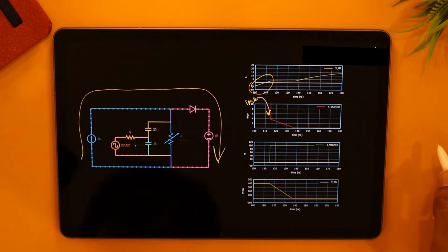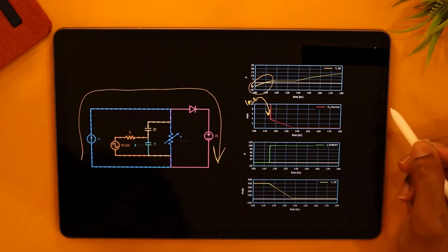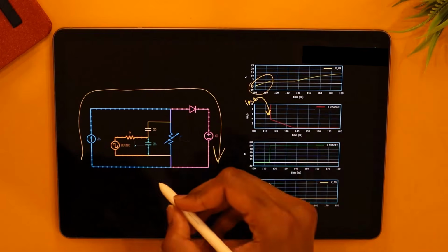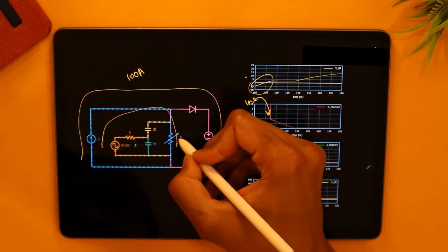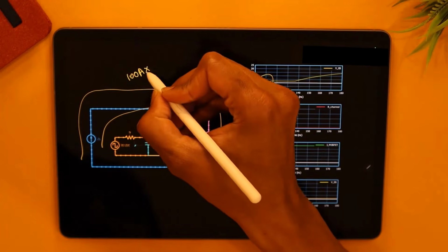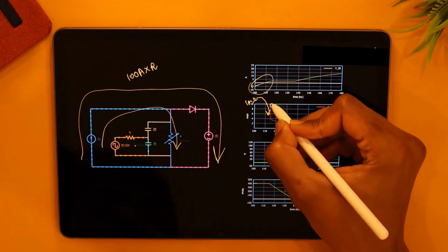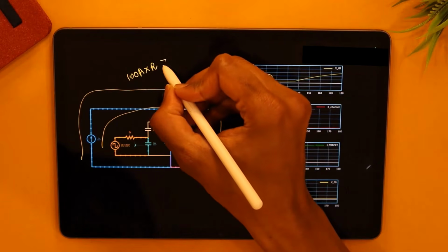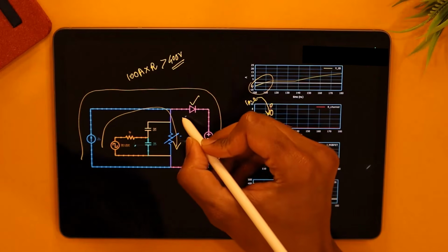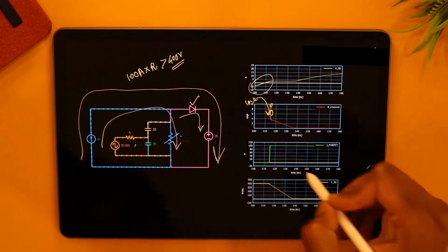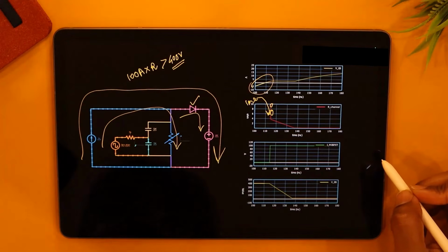This is happening because the MOSFET resistance, although it is dropping here, it's still quite high. It's so high that 100 amps, the input current, if it flows through the MOSFET, that into the resistance it is offering at the moment, something like 10 ohms or 8 ohms, that's going to be higher than the 400 volts, making this diode forward bias and eventually routing all the current to the output voltage supply. So that's why the MOSFET is not carrying any current.